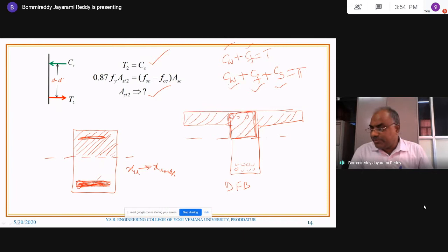The T-beams are used for increasing the compressive resistance of the concrete. And you know that nowadays most of the structural members are monolithic. That means the rectangular beam and also the slab. This is called the slab, this is slab on one side, and it is also slab on the other side, and it will be contributing to the strength of the beam.